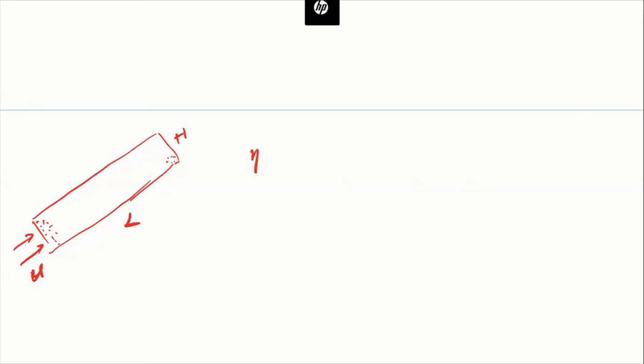So under this situation, how do we calculate the removal efficiency, right? We can still use the same method, except that now we do a force analysis, and separate the gravity into two different directions, right? I think this is something you learn from physics. We can always separate the force into several directions. So basically, if we want to separate it into the direction perpendicular to the duct and the direction along the flow of the flue gas, then we can separate that into two directions.